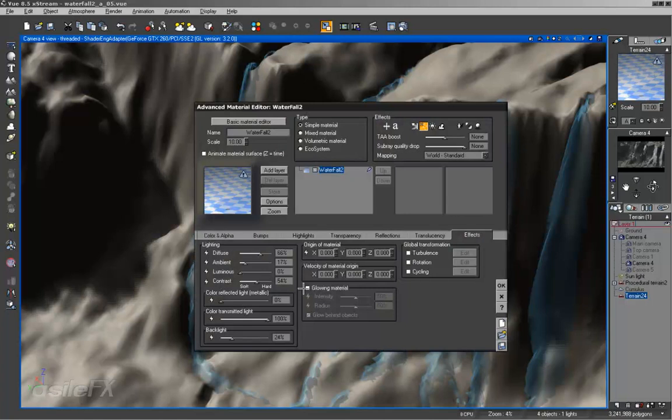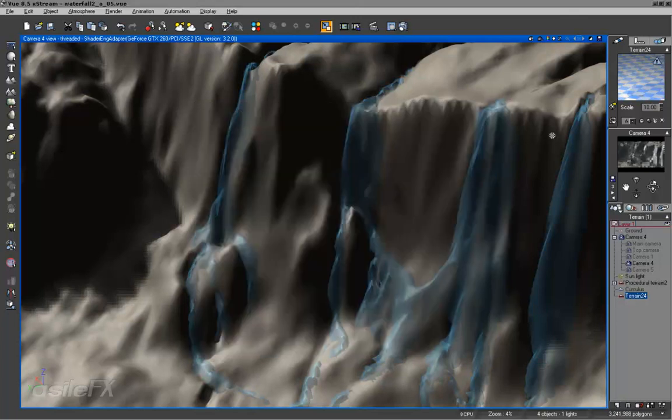I've got my contrast set fairly high. At the moment, it's set to 54. This is really going to be dependent on how detailed the terrain is. You can get a lot of different effects by adjusting the contrast. Lowering it will make a much smoother surface and the highlights won't be as intense.